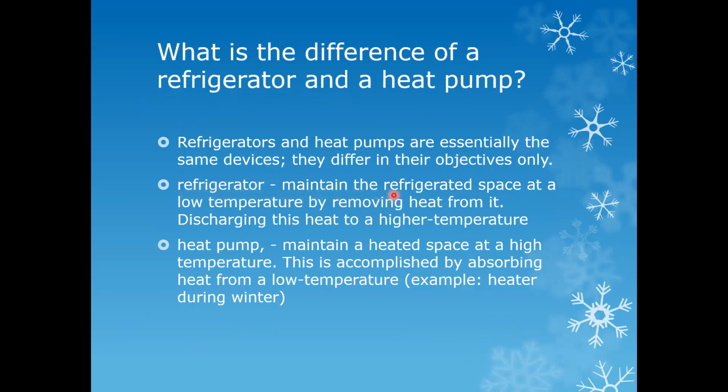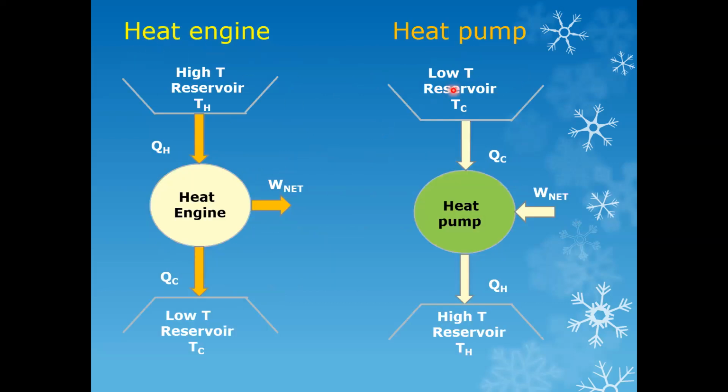In the refrigerator, the refrigerated space is maintained at a low temperature by removing heat and discarding the heat to a higher temperature reservoir. In a heat pump, okay, so let me correct. What we're differentiating right now is a refrigerator and a heat pump, not a heat engine and a heat pump.